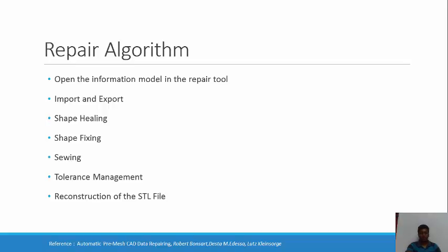Here comes the need to repair these inter-entity topological problems to make downstream applications easier and possible. In this work, most of the problems are solved fully and automatically, depending on how corrupted the IGES file is, with regard to setting the tolerance value. The sewing algorithm is tolerance driven and allows the creation of connected topology.